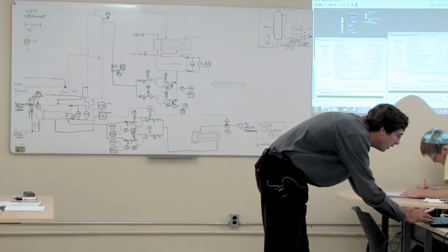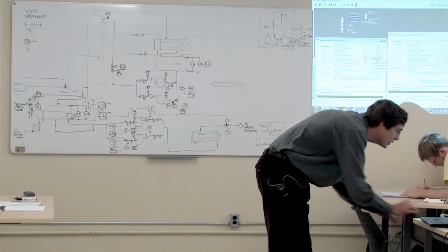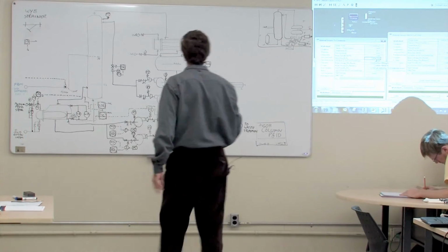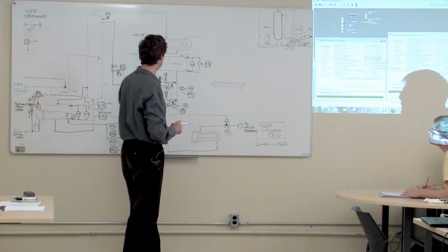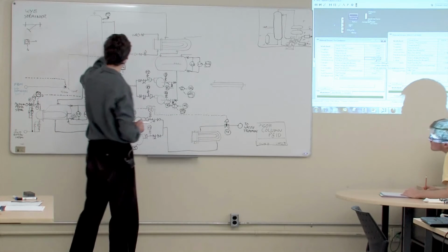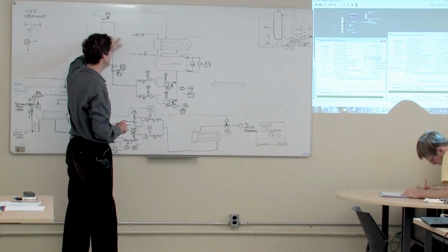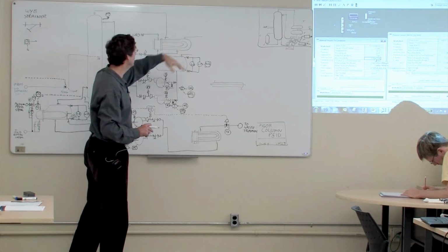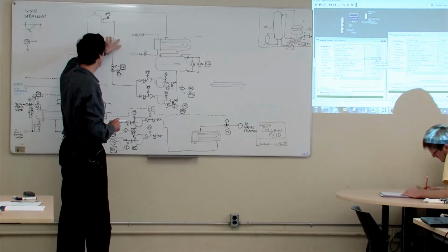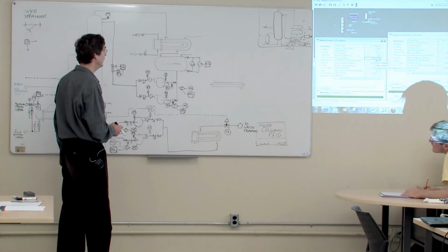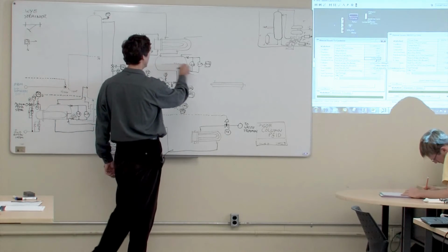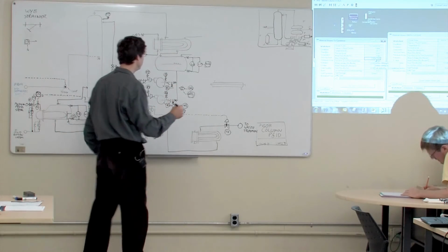And coming in, I have about 36,000. So my flow rate coming in here is about 36,000. My flow rate going off the sheet is about 17,000, which means the reflux flow must be around 17,000, assuming that the vent rate isn't very high. So it's a wash as to which one I hook up to the level indicating control.